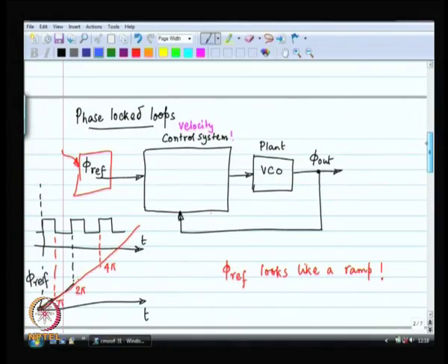Our control system over here is trying to do velocity control. Here the input is constantly changing, the input is a ramp, and that means I can't build a simple position control system with one integrator over here, right. This is what we are trying to get at. Okay.